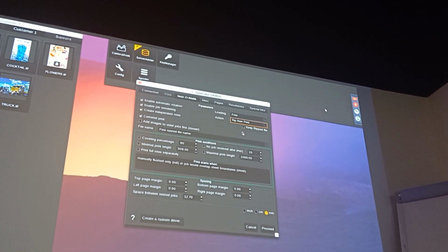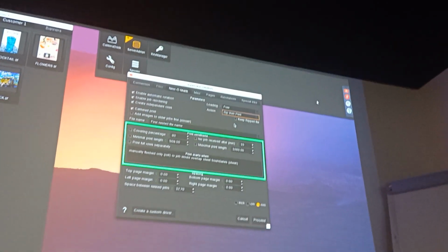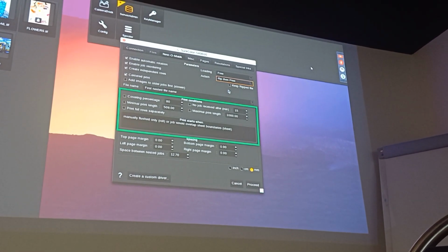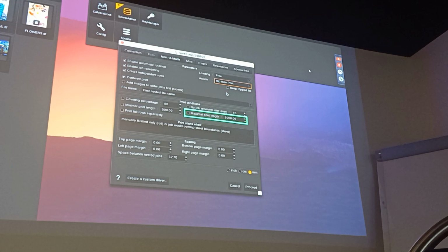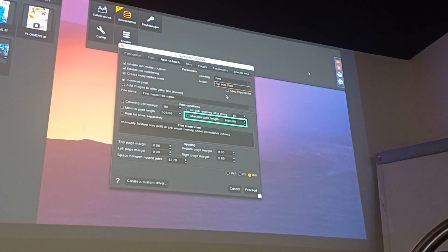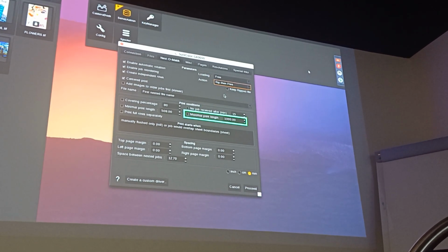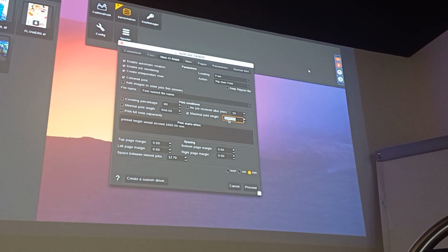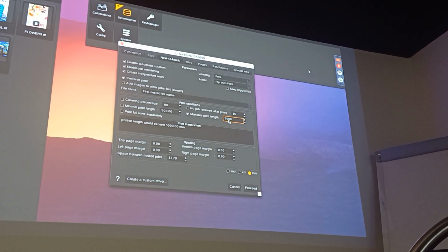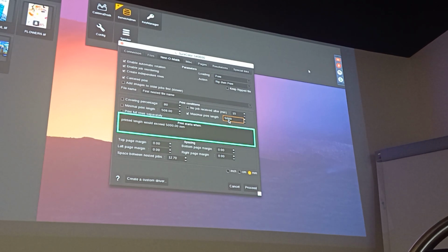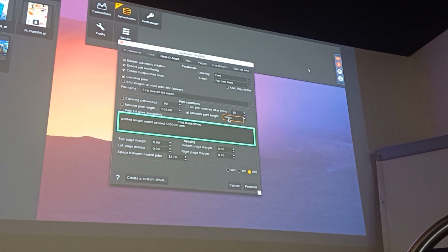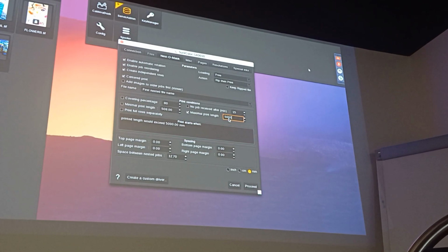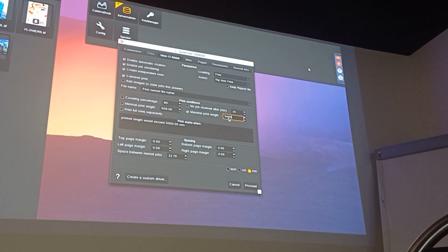Okay, let's speak now about print conditions. It allows to automate print starts. For instance, when printing with roll-to-roll printers, it is very useful to set up a maximum print length. Here, for instance, let's type a maximum length of 5 meters per AutoNest. Doing so, the print will start before the AutoNest job exceeds 5 meters long.